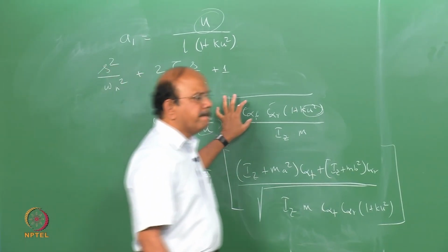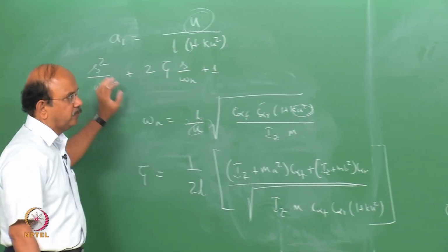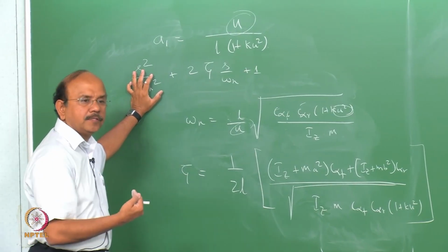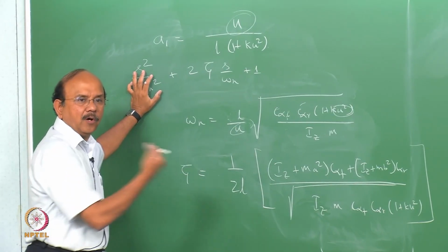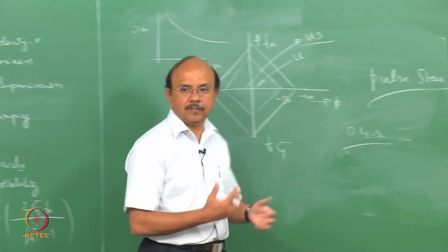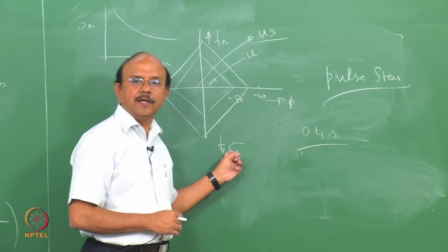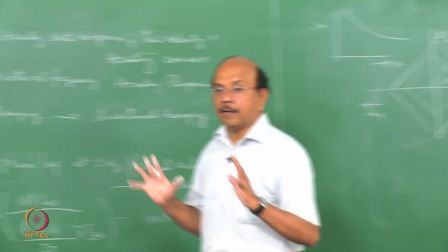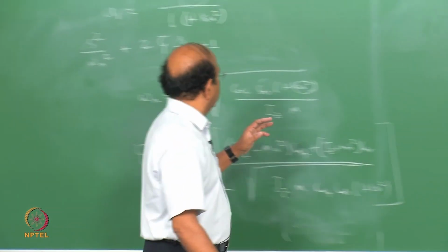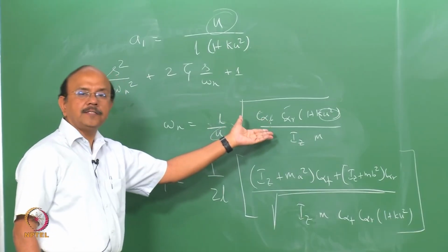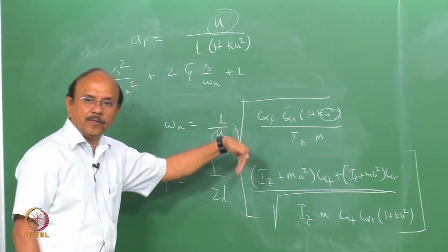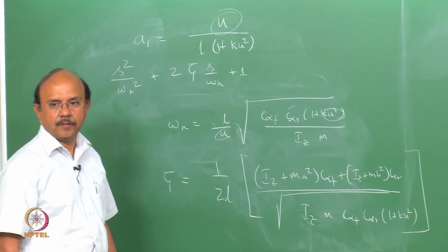Clear? In fact, we have done a lot of work on this, and we found that with an expert driver, this rhombus, which we call the Mimuro rhombus, and the subjective evaluation of a driver matched very closely. So in other words, we found this to be an excellent objective evaluation tool. So now you see the importance of tires, and we will see the importance of other things as to how they're going to be affected.